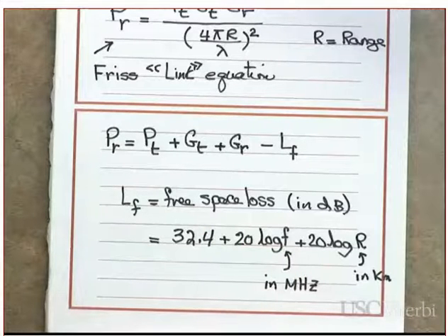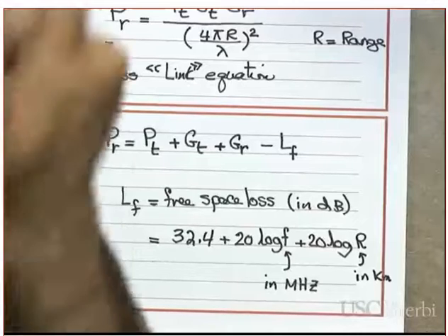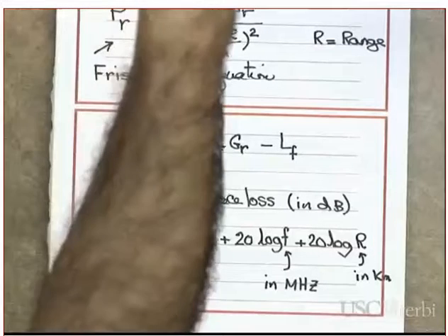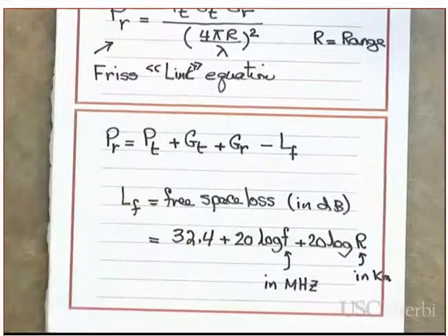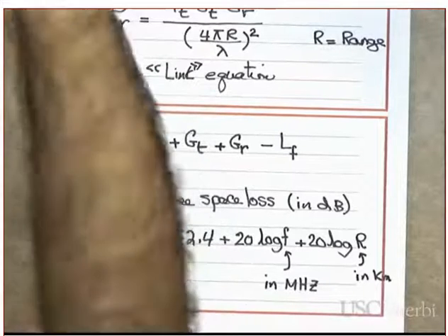One problem is if there is a mismatch between the antenna and the receiver front end, an impedance mismatch, you need to include the degradation. Yes or no? If there is a mismatch in the polarization between the transmitter and the receiver antennas, you need to take that into account. If it rains, like where?